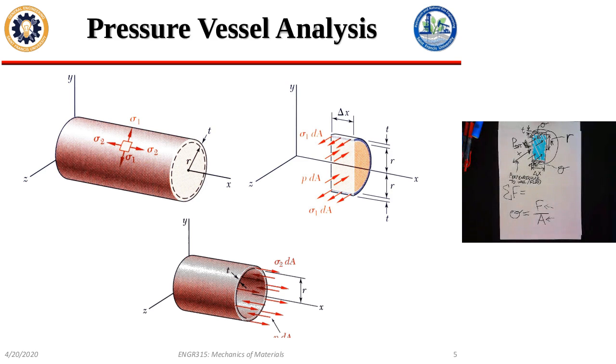You'd have to do the surface area of the section. Okay, so you do a cylinder. Well, hang on a second. The section that we're looking at here, yeah, it's cut out of the cylinder. But what shape is this actual section where all the forces are acting? So you could just do a rectangle. You got it. So what's the area of just the walls?